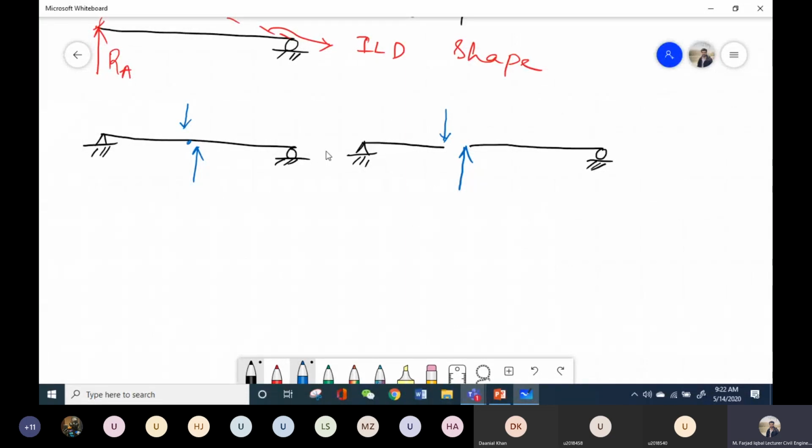These are two opposite and equal forces acting on the face of the structure. Now, in this case, how will the beam deflect? When you apply the load at this point, this part will move something like this, and this part will move upwards, right? So if I combine these two parts, the shape that I have plotted is basically the deflected shape, and it is equal to the ILD, right? It's just like a game. You have to remove the capacity of the beam to resist that particular function and plot the deflected shape, which will be equal to your ILD.